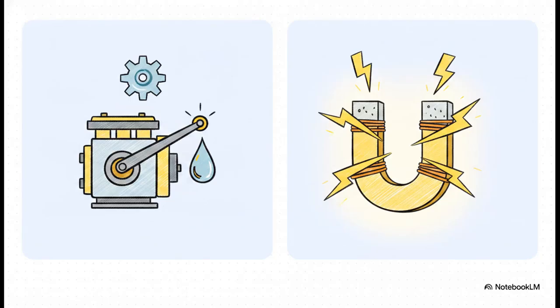Well, frequency directly mirrors how fast your engines are spinning in physical reality. To control it, the engine's governor physically drives the fuel rack. It's managing the fuel. Meanwhile, to control the voltage, the automatic voltage regulator, or the AVR, modulates the invisible magnetic excitation current.